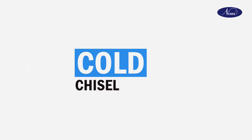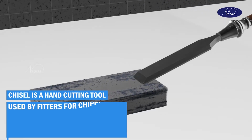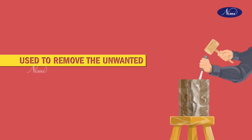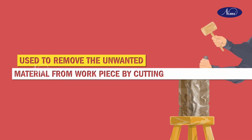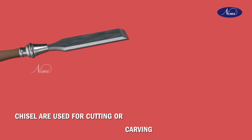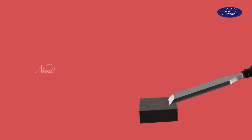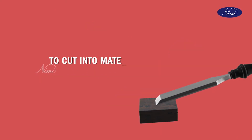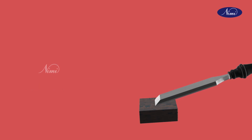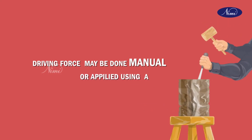Now, we will discuss about the cold chisel. The chisel is a hand cutting tool used by fitters for chipping and cutting operations. It is used to remove the unwanted material from the workpiece by cutting. Chisel is a tool used for cutting or carving hard material such as metal, stone or wood. In order to cut into a material, wood or metal, a chisel tool is forced into the material. The driving force may be applied manually or using a hammer.